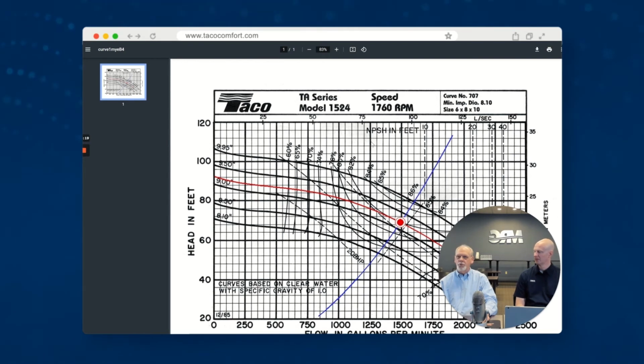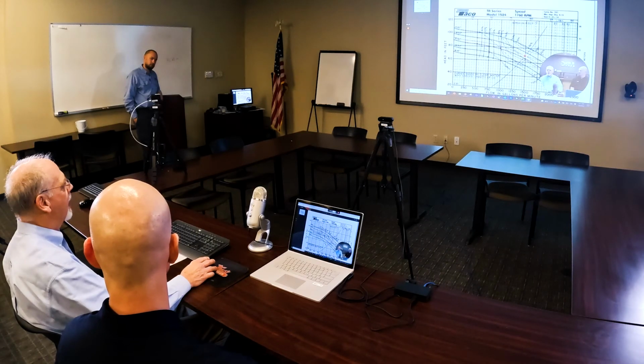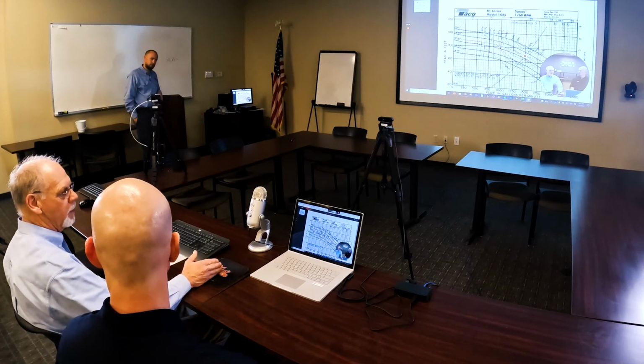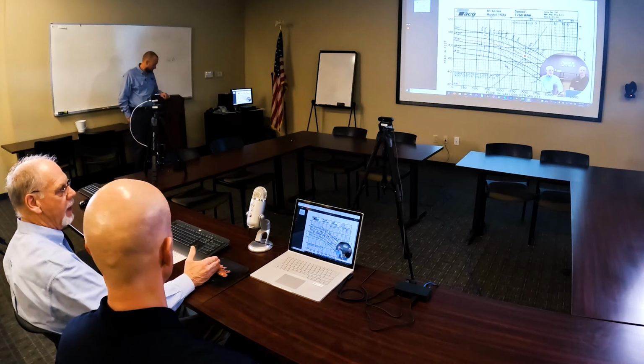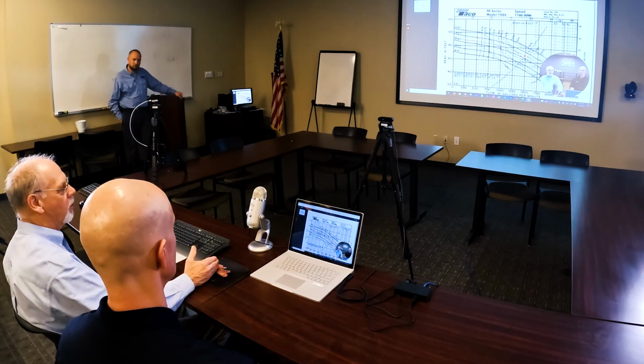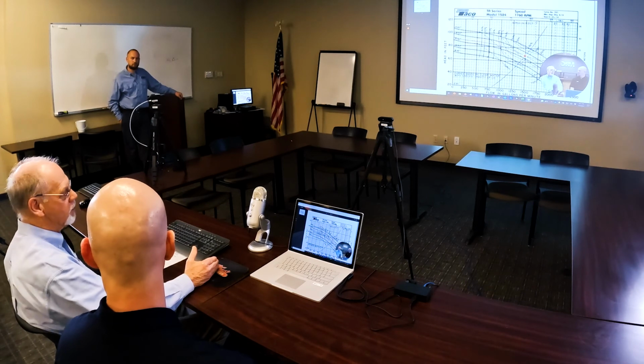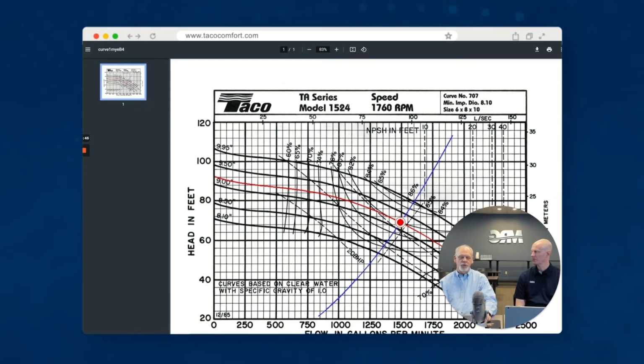Yep. The engineers put out a chart that they use to determine what the pipe size will be for any flow in a system. Most of the time, John, if you've got two pumps, they may have a smaller pipe in the vertical and tie into a common header of a large pipe. And that also gives you another way of saving a little bit of money in the installation because you're reducing some pipe sizes. So a reduction in pipe size will be a reduction in your cost. Also, a reduction in fittings is a reduction in your cost.